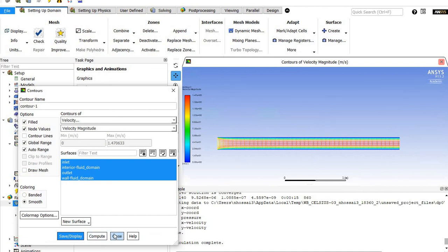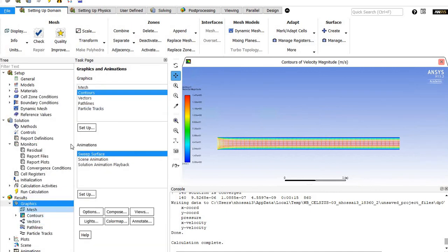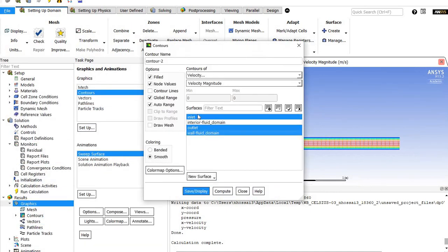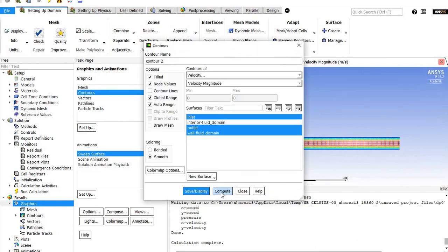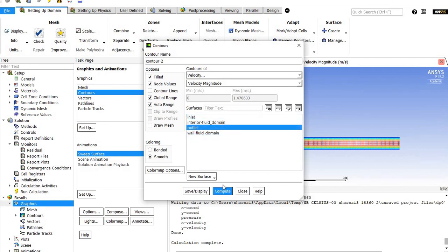Okay. If you want to calculate any specific property, average property, you could have done it in here as well. Like I wanted to check the outlet velocity, let's say. So outlet velocity, I can do compute. It should show, oh, sorry, compute. As you can see, the max velocity is this one, minimum velocity is this one.